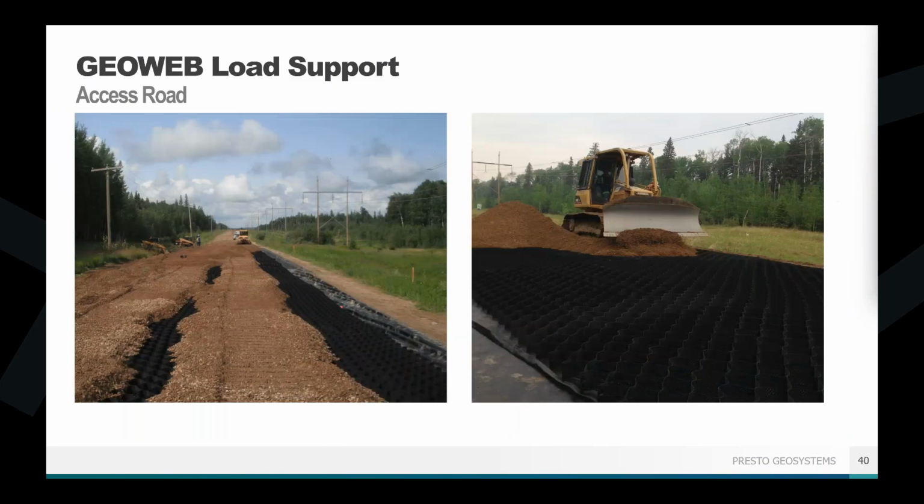We used some bobcats and excavators to completely move all of those materials from the stockpile, and then a dozer was used to finalize the grading of the road. In this case, it was a dozer that was equipped with that GPS sensor at the bottom of the dozer blade to help ensure that consistent final wear surface. Pretty common nowadays. It was kind of neat the first time we used this. Like I said, this project's a bit older, but pretty commonplace nowadays.